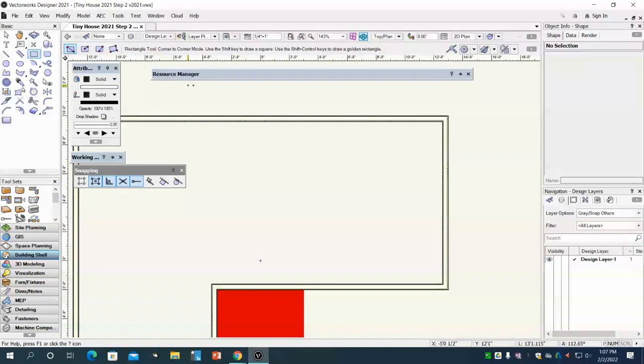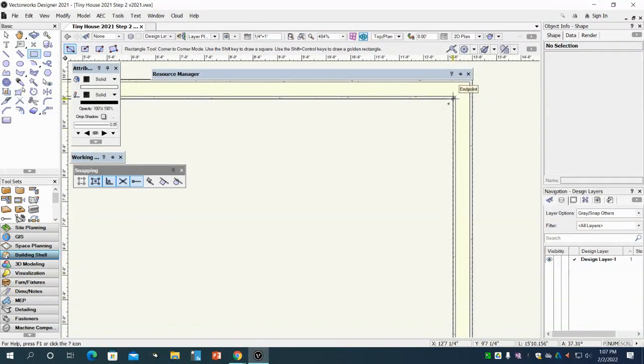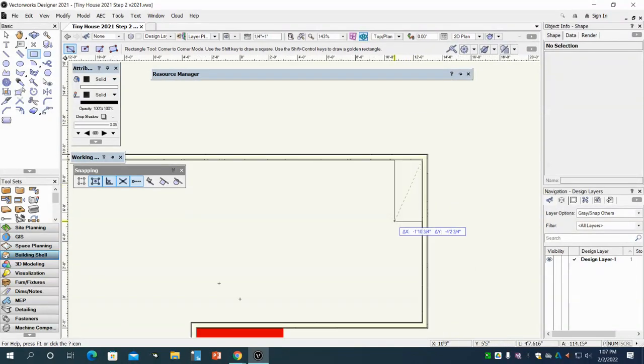In this case, I am going to use layer plane instead of screen plane. That way, when I move the project around using the flyover tool, my rectangles will move just like they're a part of the floor. So to get started on this, I'm going to zoom in and carefully click on this corner of the inside edge of the drywall right here and drag this rectangle down.